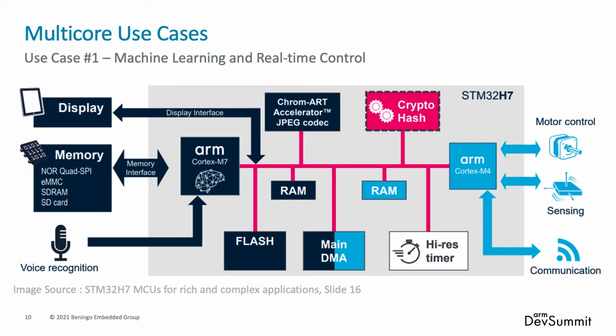But the idea there is, if you're using a heterogeneous processor, you have the feature-rich side running the ARM Cortex-M4. You have that do the machine learning, run the inferences. You have the M0 Plus side do motor control, actually do the ADC conversion, sample the sensors, maybe perform real-time communications as well. But the idea here is that we really have two separate problem domains. One is running inferences and machine learning algorithms, and the other is handling real-time control. So we can separate these into two completely different cores, which then, of course, gives us lots of advantages.